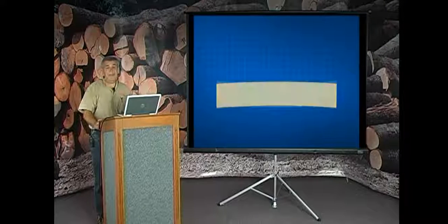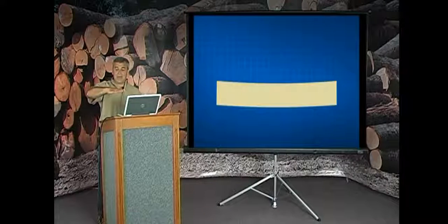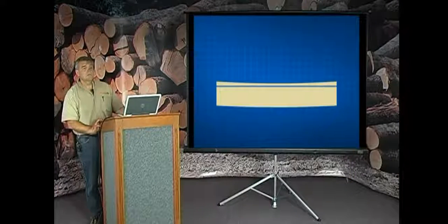When you see that happening and you roll 180, what you're going to notice is that the ends are high and the middle is low. And it might be slight, or it could be a considerable amount. And you've got a decision to make. Do I cut another board knowing that my ends are thick and my middle is thin? Is it close enough for who it's for, close enough for what it's for? Or do I go right back where I was on that last cut and make a cut with that log having been rolled 180 degrees?